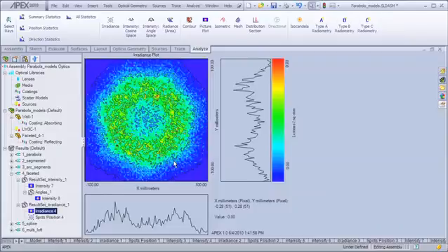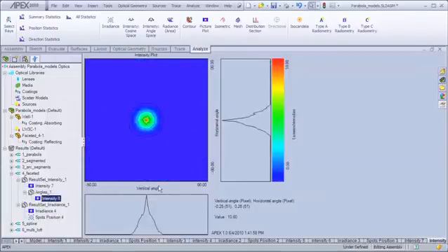So this has been a significant improvement upon any of the previous designs, although obviously we could make it a little bit better still. But we also have to remember that I have the detector surface at one fixed location, and typically what we want to be able to do is to illuminate over a wide range of distances, which means we need to have a narrow angular spread. And in this particular case, what we see is, yes, we're getting a good energy distribution, but at the cost of having a somewhat wider spread of energy, although in this particular case, most of the energy is within, say, a 10-degree bundle based on the information we see down here.